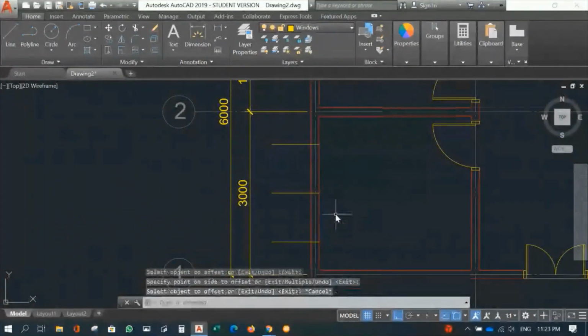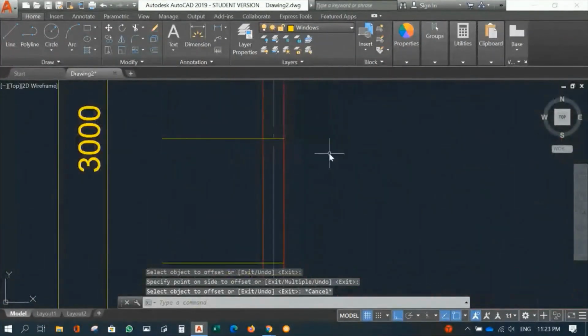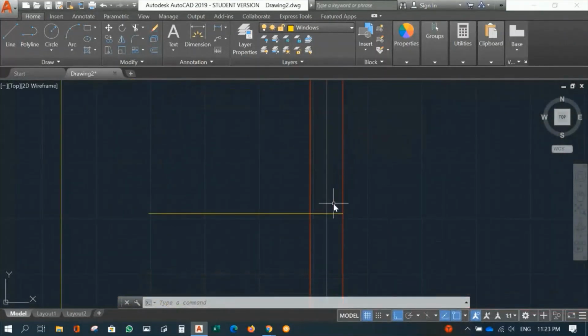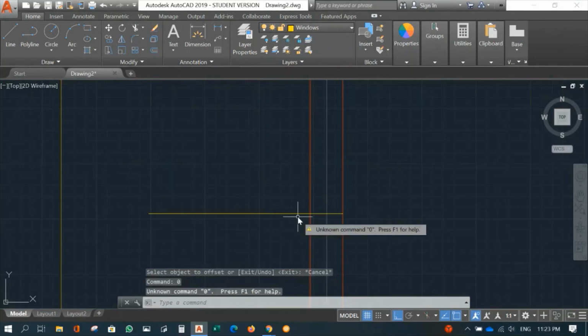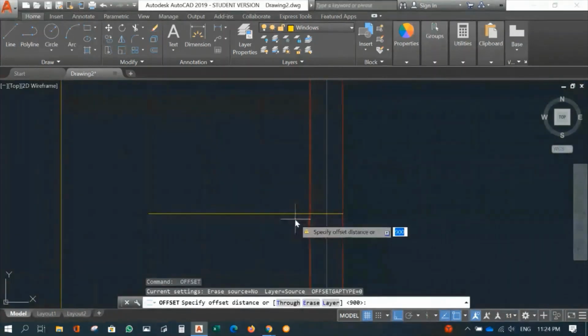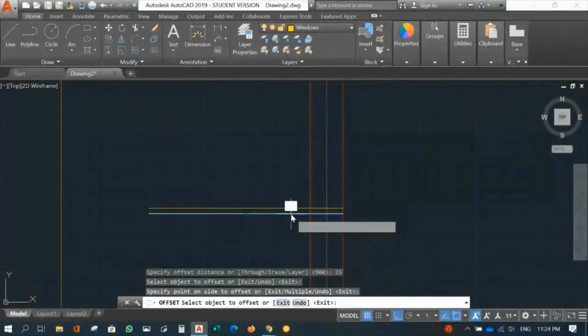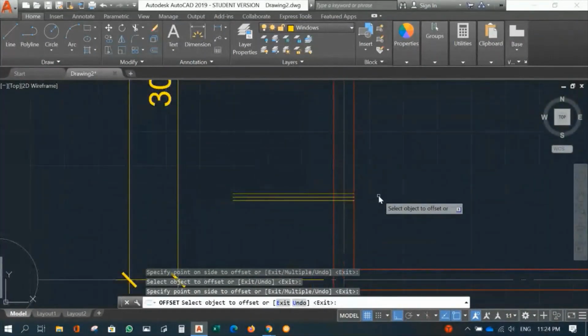And then once I have that, I'm going to create a window jam here, right? So I'm going to offset. So the size is 50, right? So I'm going to offset 25. This bar, 25, this bar, at the top and 25 to the bottom, right?